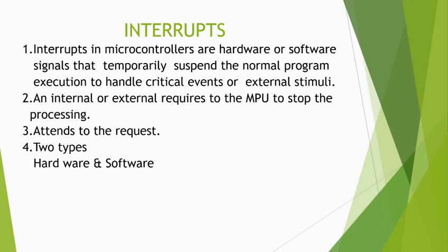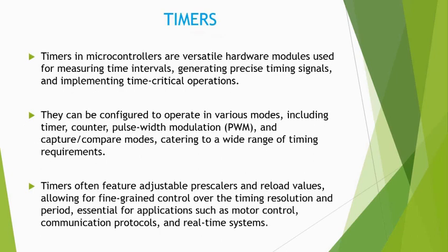The next slide is of timers. Timers in microcontrollers are versatile hardware modules used for measuring time intervals, generating precise timing signals, and implementing time critical operations. They can be configured to operate in various modes, including timer, counter, pulse width modulation, and capture compare modes, catering to a wide range of timing requirements.